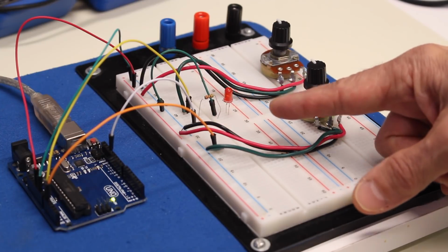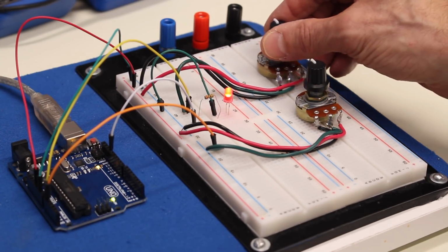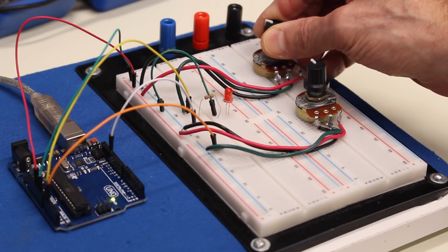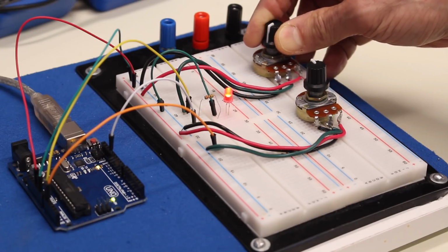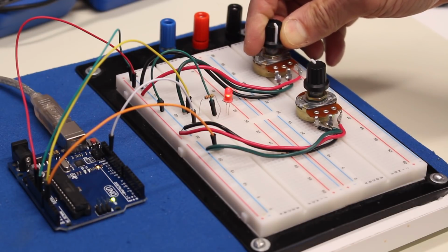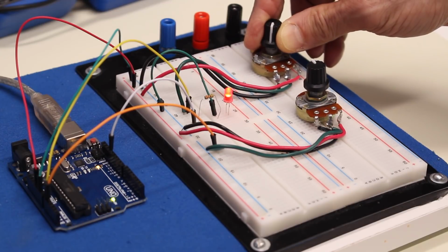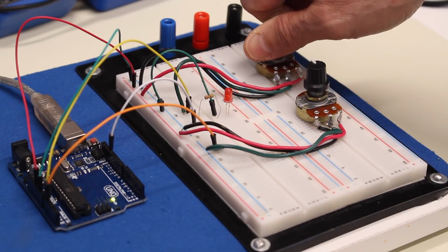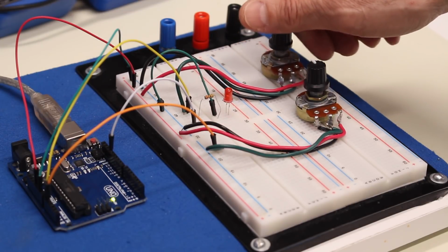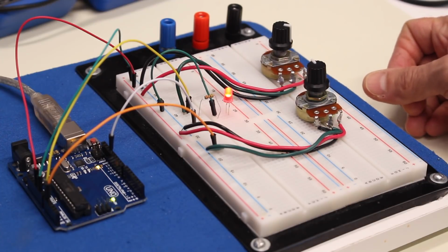Okay, so as you can see, my LED is blinking a bit faster now. This is the pod I've got connected to analog A0. If I move it down over here, you'll see it goes faster and faster until the point that it's blinking so fast that I really can't see it with my eye. So very fast blink. And if I go all the way to the other end, which will give the pod an output value of 1, I'm back to the original blink speed.